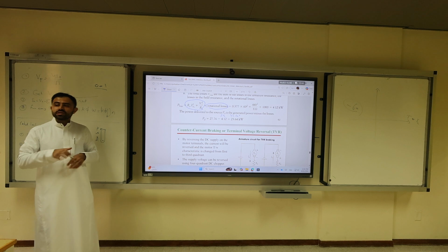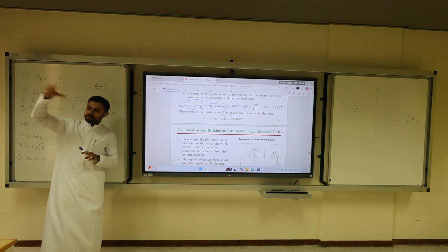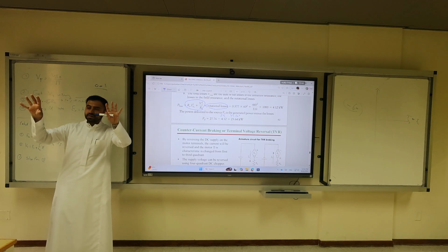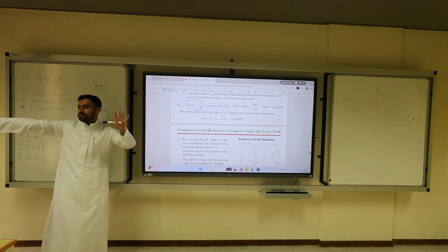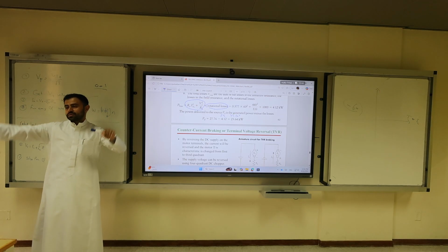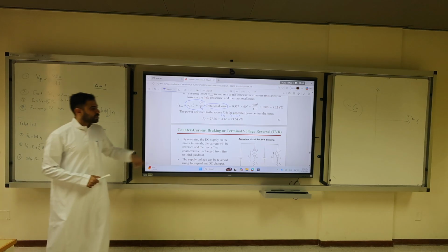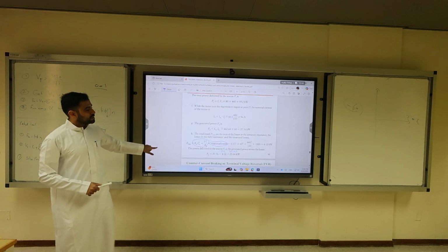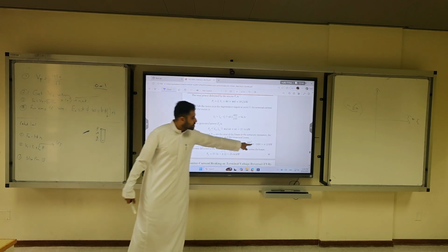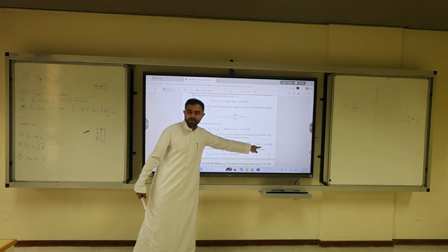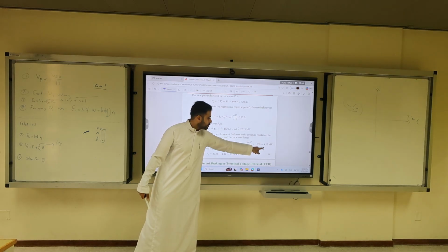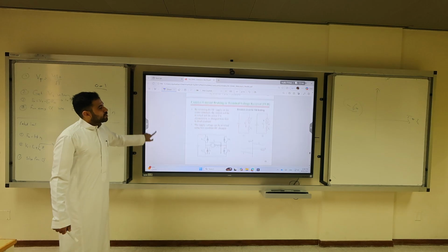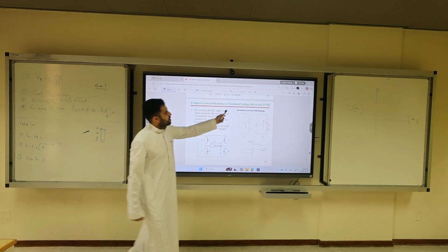Why may rotational losses not be counted when we do regenerative braking? Because the power exchange is purely electric. Yes, at the shaft, we have to subtract rotational loss. Where did you get 3.12 from? It's electrical minus 1,000. There is no 1,000 rotational. It's 4. Yeah, if you add 1,000, it's 4.